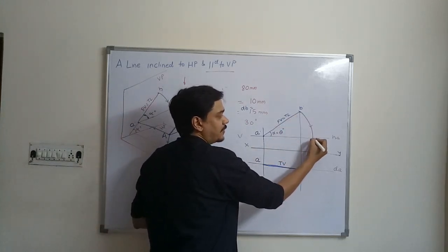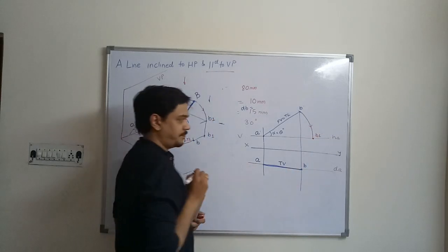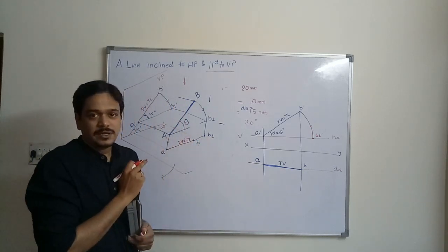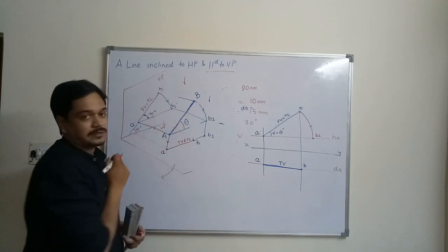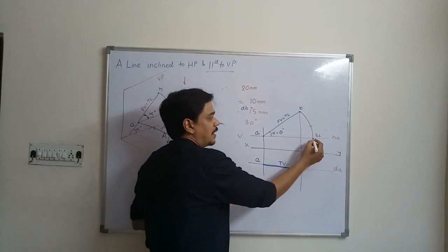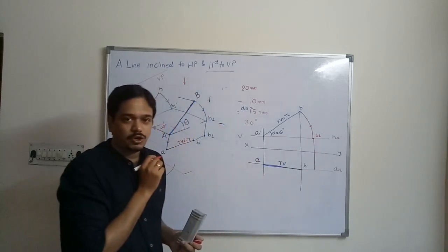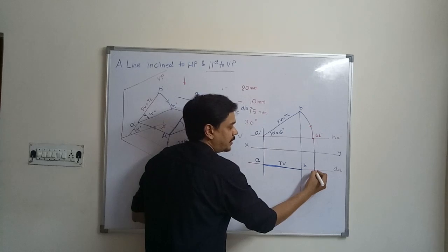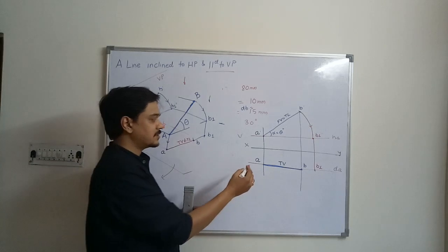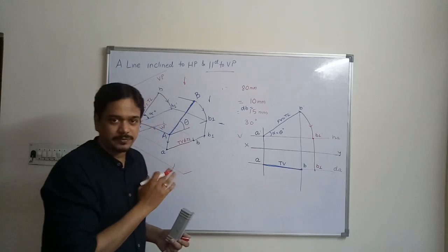So this is the rotation of the front view. This point I am naming B1 dash. So A dash and B1 dash is that line which is representing the front view. Similarly, I will project this B1 dash point over here in top view. So you will get point B1 in top view. As discussed earlier, A dash is above point A. Similarly, B1 dash is above point B1.